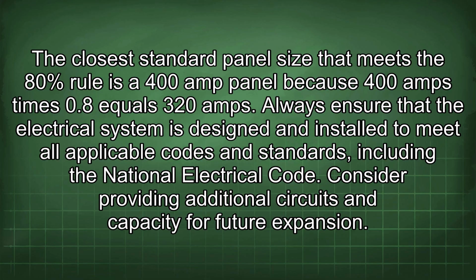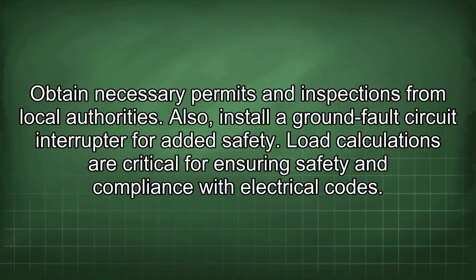Consider providing additional circuits and capacity for future expansion. Obtain necessary permits and inspections from local authorities. Also, install a ground fault circuit interrupter for added safety. Load calculations are critical for ensuring safety and compliance with electrical codes.